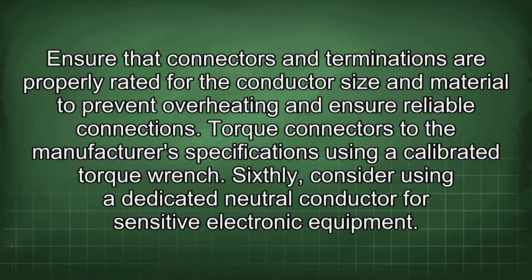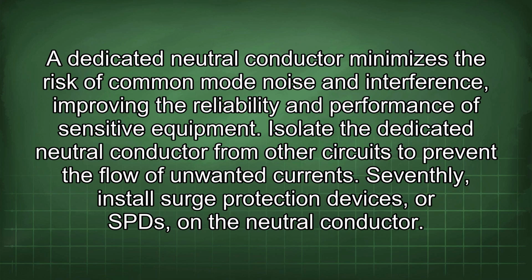Sixthly, consider using a dedicated neutral conductor for sensitive electronic equipment. A dedicated neutral conductor minimizes the risk of common mode noise and interference, improving the reliability and performance of sensitive equipment. Isolate the dedicated neutral conductor from other circuits to prevent the flow of unwanted currents.